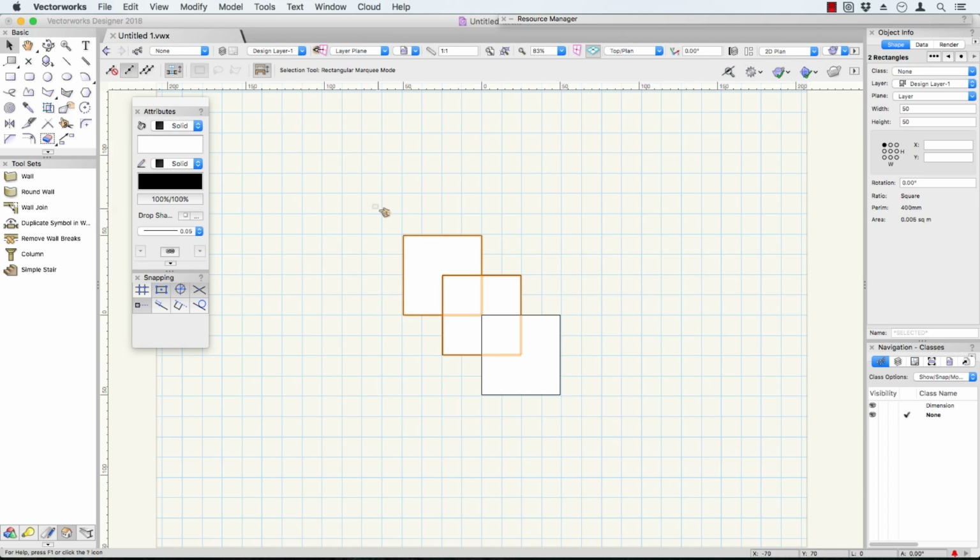The other way is to hold our mouse down, so we just hold down the mouse button, drag this marquee, and as we totally enclose an object, it becomes pre-selected. Come down to here, and you can see it's pre-selected those 2 items. Now when I let go of my mouse button, those 2 objects will be selected. And there they are, 2 objects.